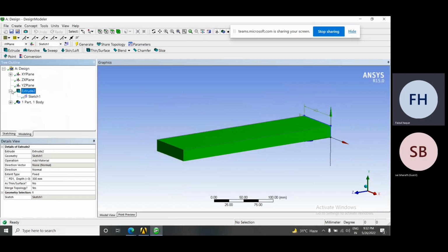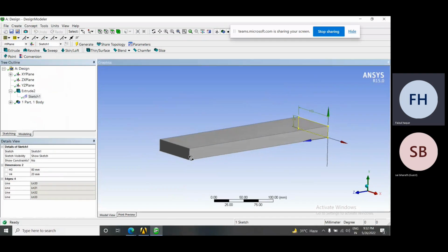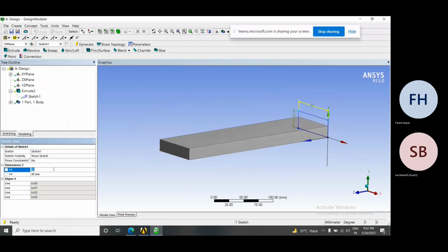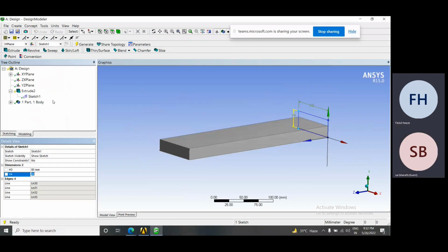Now in order to reduce the deformation here, we may change the parameter of this, like we can change its thickness from 20 to 30. This is done by consulting and by seeing the designing criteria and parameters, that what we can change, what are the resources that are available within ourselves, if we can change the cross section size. Suppose now we can talk to our manufacturer, and from there we can consult whatever parameters we can change.